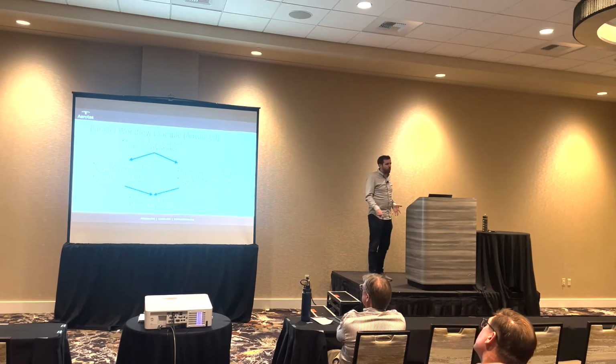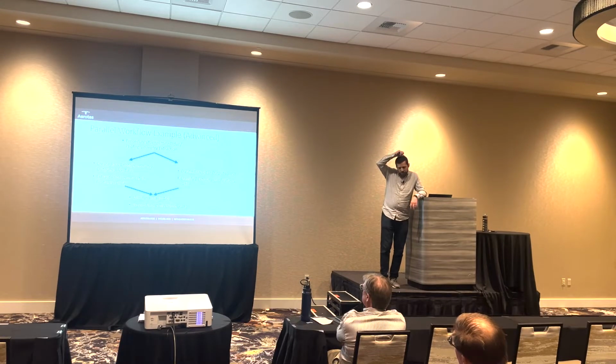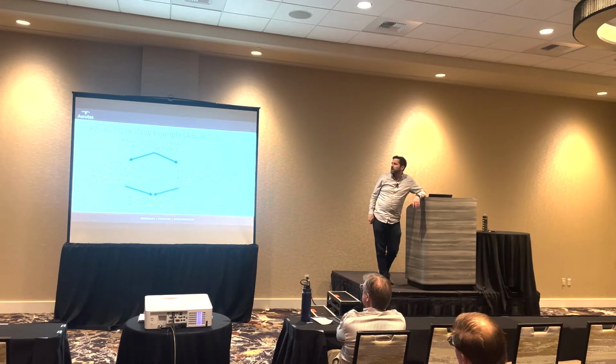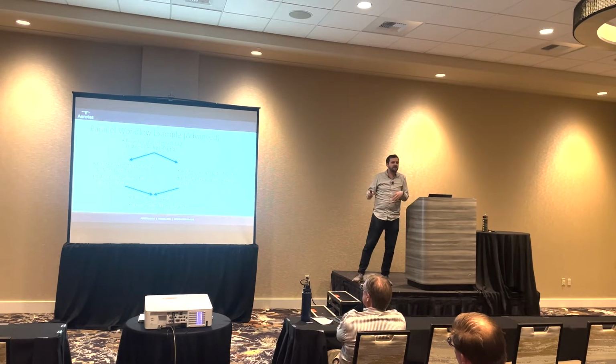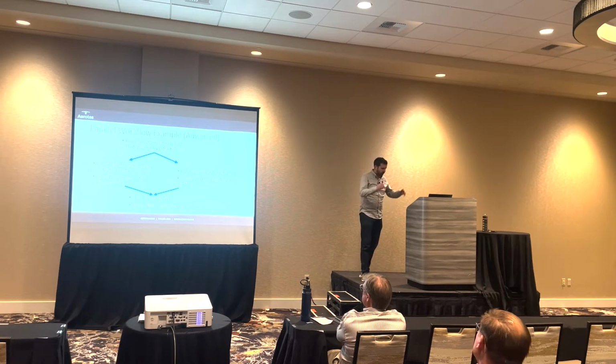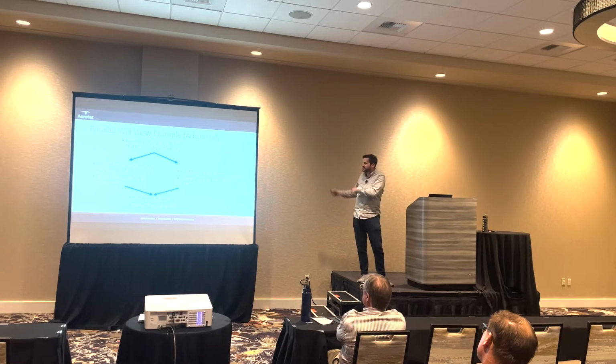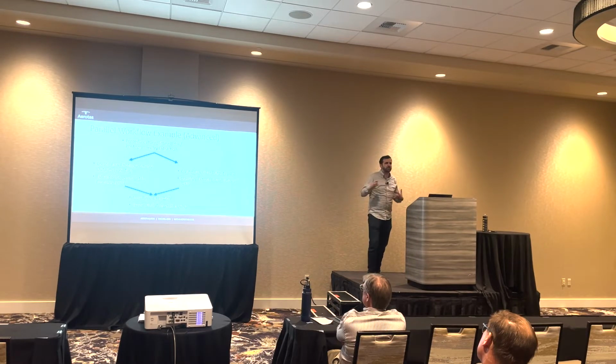CAD is where those two different data formats finally meet each other, and then you export your final deliverable. Whereas the more parallel workflow, like I said, is going to be having teams do your LiDAR processing and your photogrammetry processing at the same time. But the most important part of this is the top step, having good procedures for splitting LiDAR and photogrammetry data, so that you are clear that in vegetated areas we use the LiDAR data, because there is no good photogrammetry model for getting surface data. With LiDAR, that's where we get all the vegetation. But if it's hardscape, paint striping, roads, curb lines and center lines, then we want to get that out of photogrammetry. Your teams know what they're going to do.